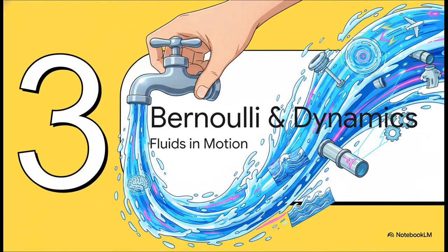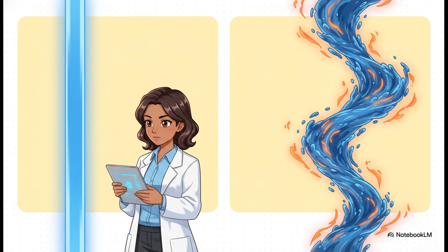Section 3. Bernoulli and fluid dynamics. Fluids in motion. Let's turn the tap and get things flowing. When analyzing system designs, engineers have to clearly differentiate between the theoretical math of an ideal fluid, which is incompressible, frictionless, and steady, and the harsh, viscous reality of an actual fluid. If you assume a fluid is perfectly ideal out in the field, you are asking for trouble. Real fluids have internal friction, which inevitably leads to viscous resistance and energy lost as heat.